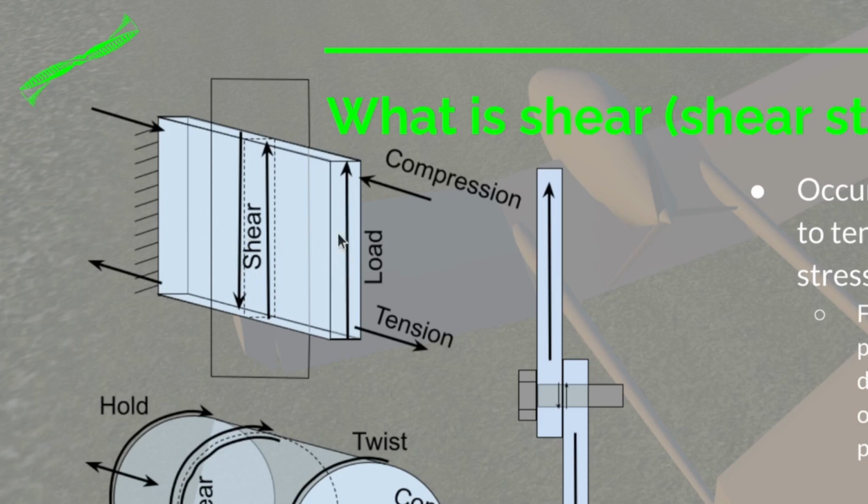Now since we have a point load here, that shear is going to be the same all the way throughout this spar. Now on a distributed load, where instead of a point load out here, we have a load all along that spar, and we have the fuselage.